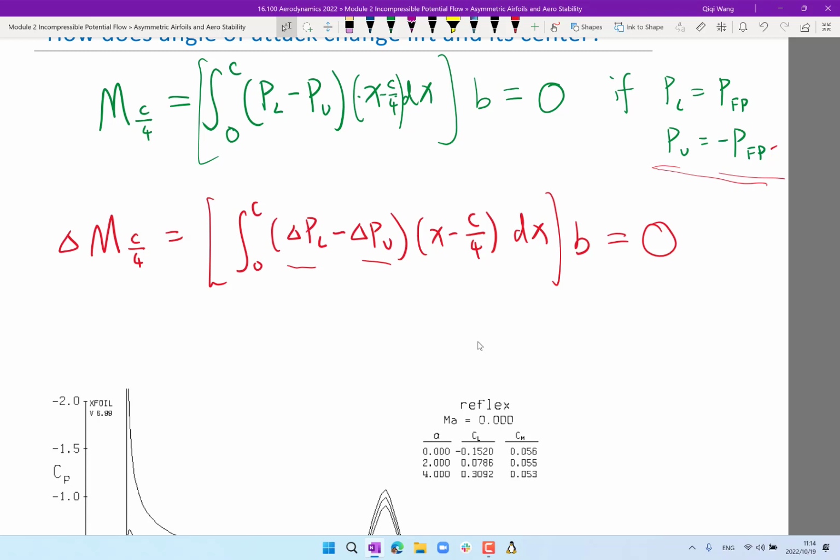Yes, that's the most important lesson we get from thin airfoil theory, right? And up to the precision of the assumptions of thin airfoil theory, this is true. Basically the difference in the CM you can see here gives you really how accurate thin airfoil theory is. All right, does that make sense?